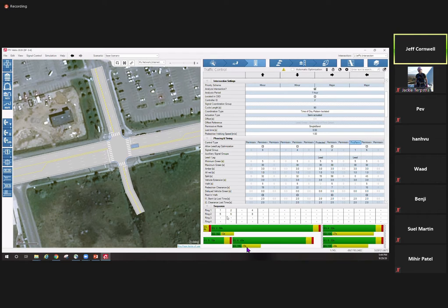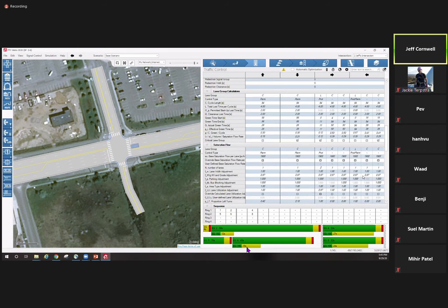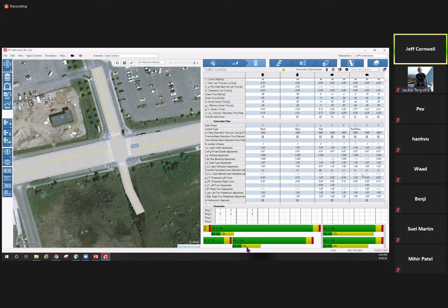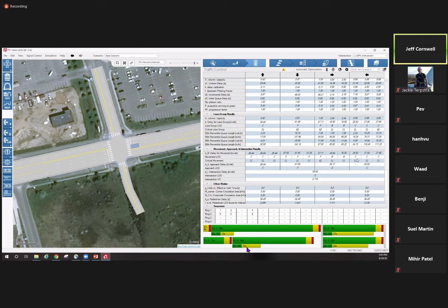It's now going to change. You see a 1 in my diagram. You want to go through and make sure all of these numbers make sense again. They do. 3-second amber, 1-second all red probably makes sense. 2-second, 3-second extension. So I think the numbers that were added were all fine. So you scroll all the way back down. And lo and behold, now it's level of service C. So you've improved that movement.